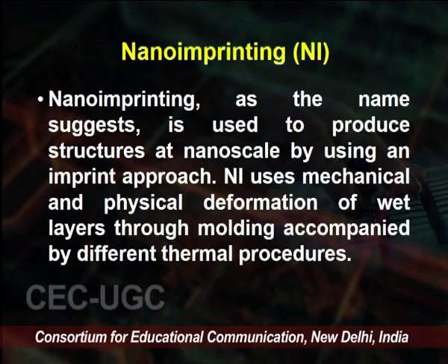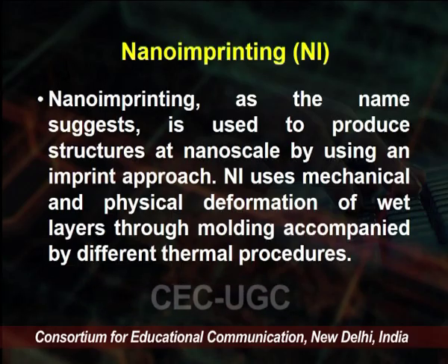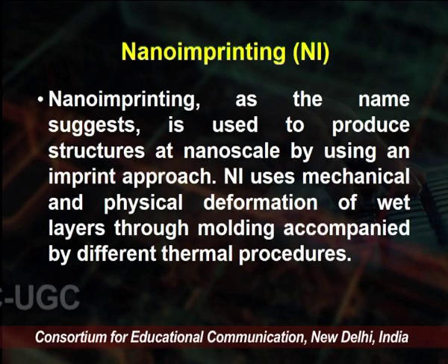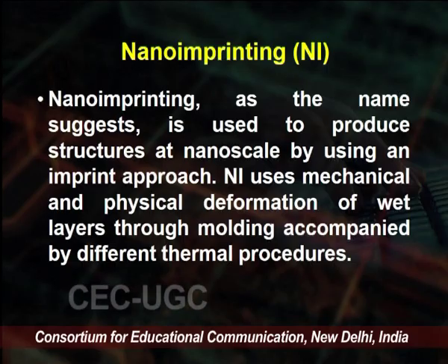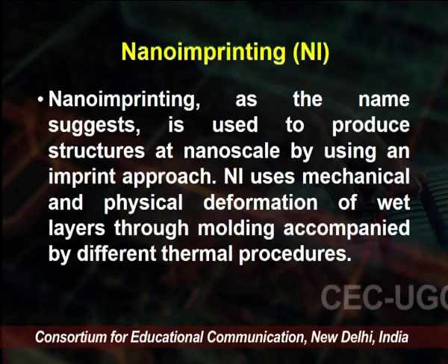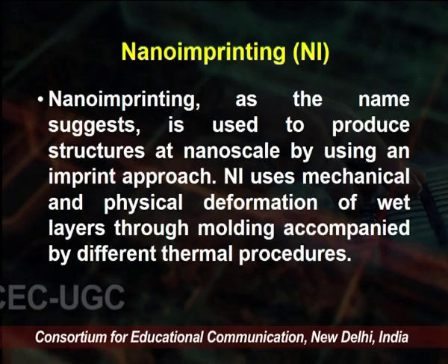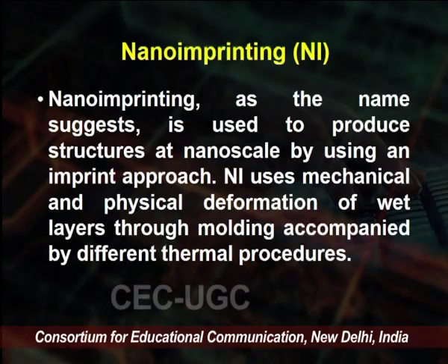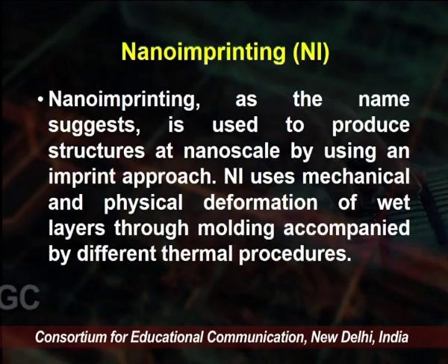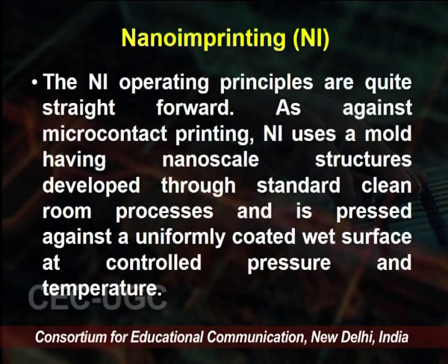As the name suggests, it produces structures at a nano scale by using the imprint approach. Nowadays devices are being miniaturized, so for that we use nano imprinting. Nano imprinting uses mechanical and physical deformation of wet layers through molding accompanied by different thermal procedures.